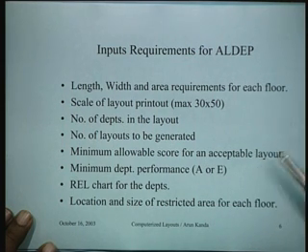In the beginning, when you run the program for the first time, you have no idea what the score will be. So the first time you generate 10 layouts, say, and maybe the highest score is 120. The second time you run the program, you can specify the minimum allowable score for the layout as 120 and run the program again, and maybe on the second run you generate 20 layouts and the highest score that you generate is maybe 250.